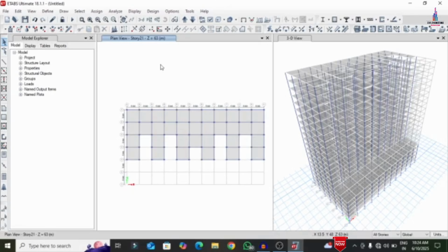Okay. Now after this we have to delete some more properties, which will make the model vertically irregular. For that, I am selecting the 21st story. Instead of the all stories option, I am selecting the one story option. I am selecting this left hand side portion. Again I am selecting the right hand side portion so that it will select story number 21. Again I will come to the bottom. Again I will select one more section, left side one, this one, 2, second story, this one. Again I will select third, this one,